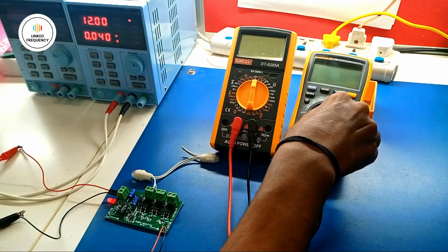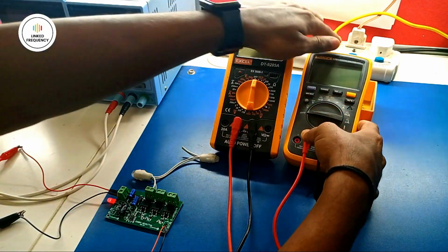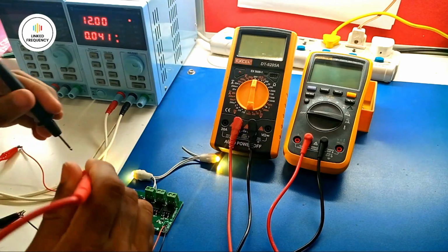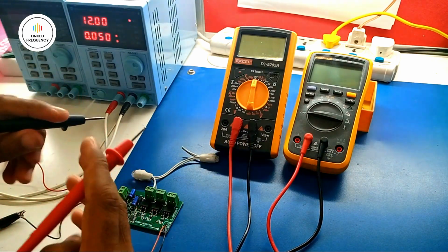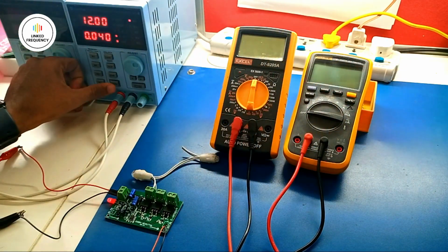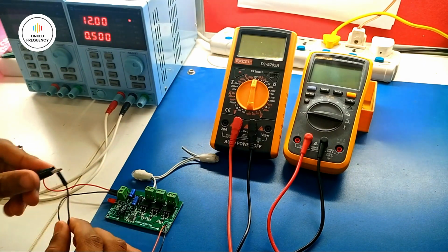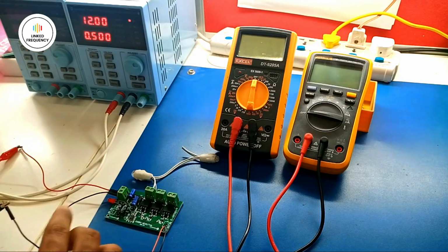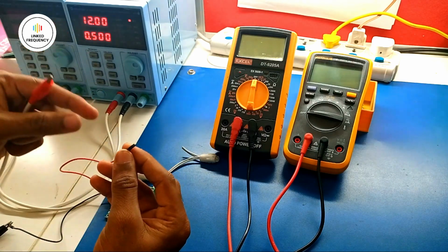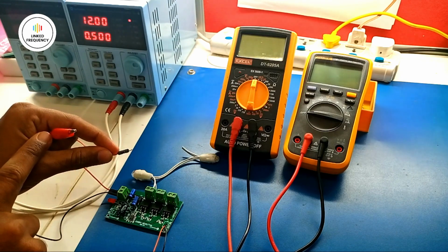Similarly, in the Fluke also, we have to change from the voltage section to the current section, which is the milliampere section. And then let's connect it in series. How to connect it? Of course, you should not connect it like this. If you connect it like this, it is going to damage the multimeter permanently. So for that, I just need to turn off this circuit and then remove the positive probe from the power supply to this, whichever is suitable for you. So I'll remove the positive probe, and we have a positive pin of this particular circuit here and the positive pin from the power supply here.